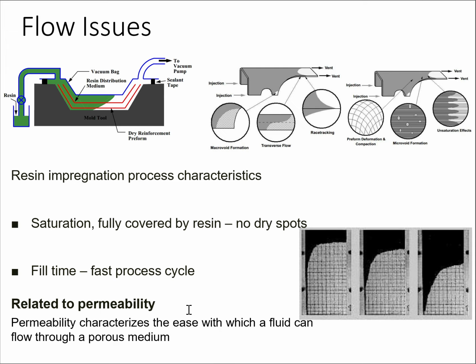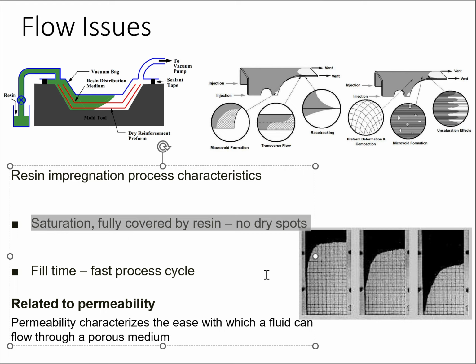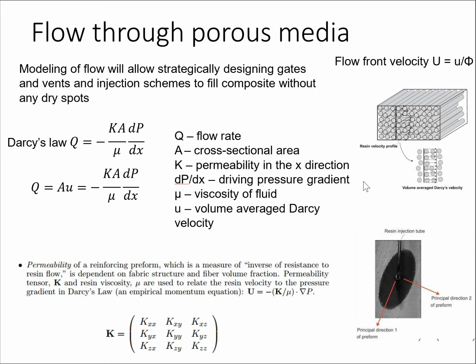You want to make sure that during the VARTM process, you don't leave a dry spot. And how can we make sure of this? We want to make sure that the distribution media covers all of the carbon fiber or the glass fiber, whatever you're using. The dry spots are going to create problems eventually in the strength of the material, because essentially you are going to have these air bubbles, and these are going to be the reason for deformity, for failure, for rupture in your media. So you want to make sure that everything is completely covered.